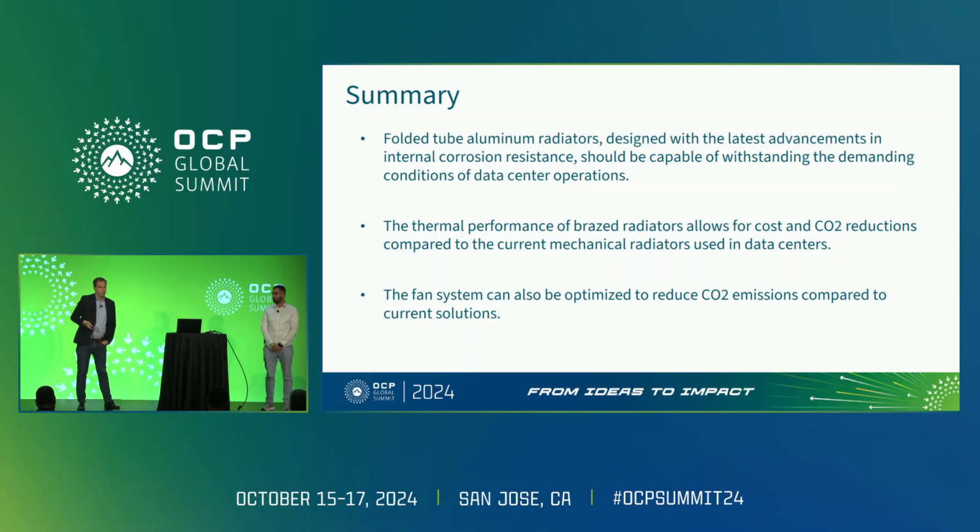To conclude, if we are definitively facing some problem with the internal corrosion test and internal corrosion reliability, we can think about the coolant that we are using. It's not the purpose, again, of this conference, but we can imagine using what is used, for example, in the automotive industry. What we call glycol is in fact propylene glycol with corrosion inhibitor or similar, to help the system introduce heat exchangers with aluminum material.